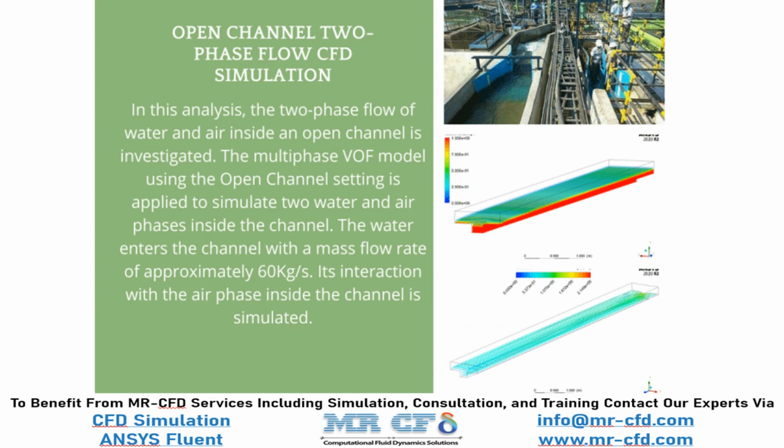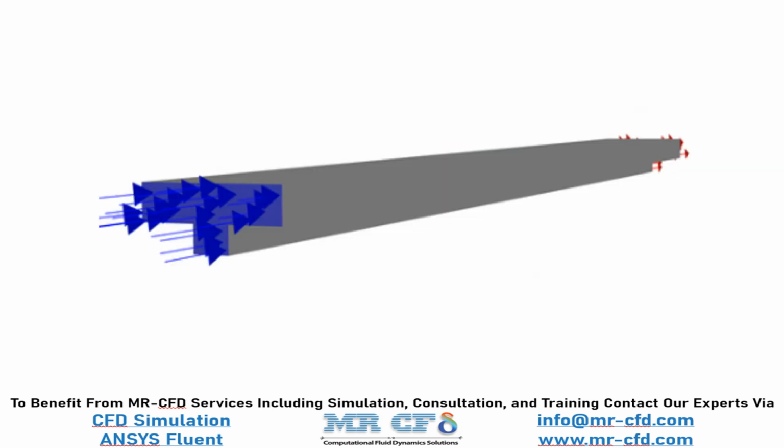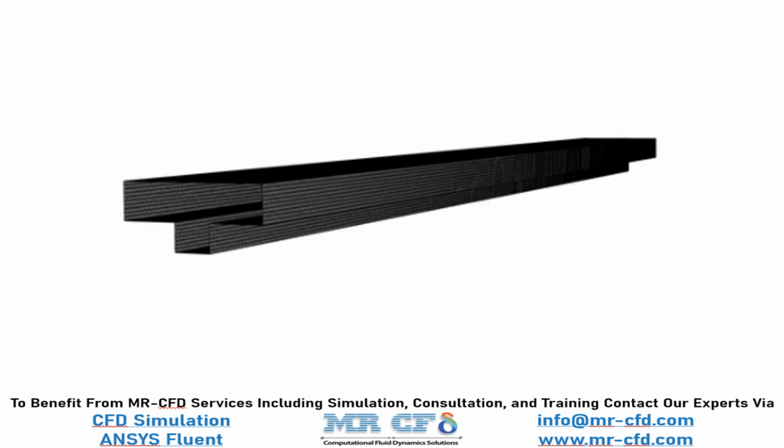In this project, we will simulate the air and water flow inside an open channel. The geometry of the present model is designed in ANSYS Design Modeler software. The geometry of the present model is meshed inside ANSYS meshing software, and the mesh type used for this geometry is structured.